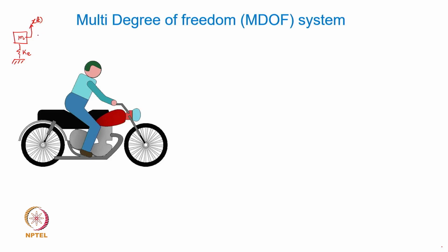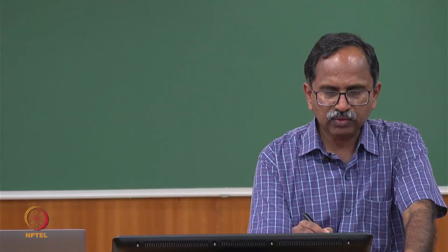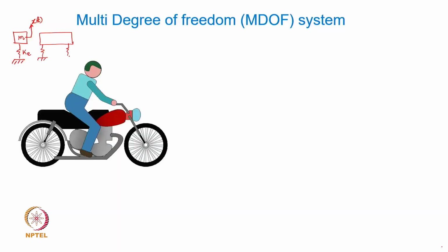Later on we discussed that for a car, an automotive which has maybe a different suspension characteristic, we also look at other degrees of freedom which could be important. So, this kind of a pitch motion, this kind of a bounce or a heave motion, we included. In that case an additional tilt degree of freedom, the angular motion theta, and the heave or bounce motion like y.